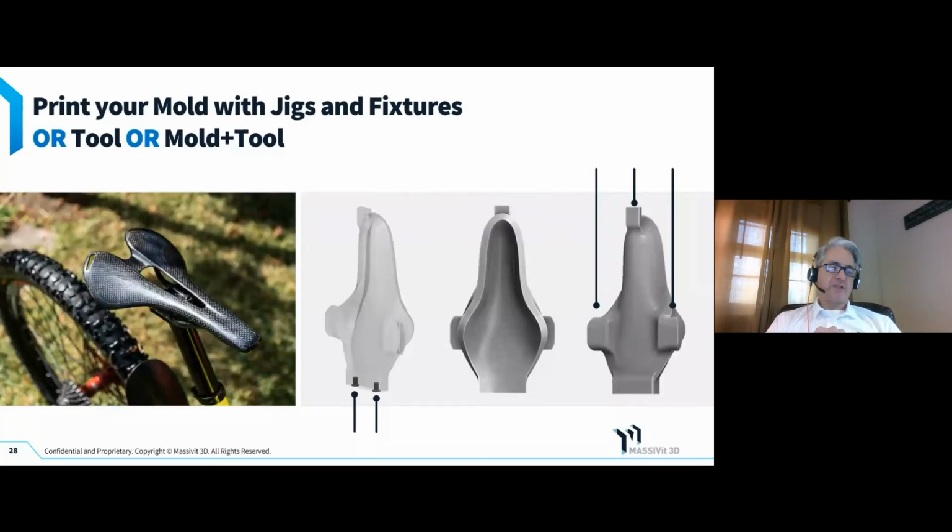And in the process of printing, we were also able to print around these inserts that you see on the left of the three mold views. Those inserts are placed on the table, and we print around them, and then we pour, and they become an integral part of the mold, and they're now considered your datum for machining. So as you're setting this up for machining, now you have a machine surface, these PEM type inserts to touch off of for your datum point, for your machining to make it more accurate.